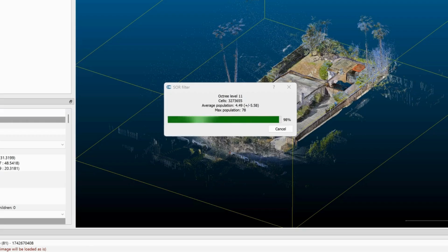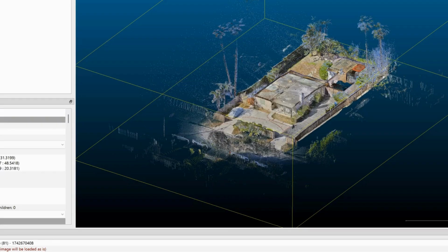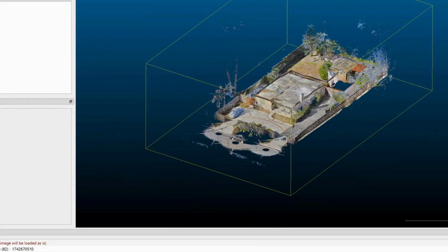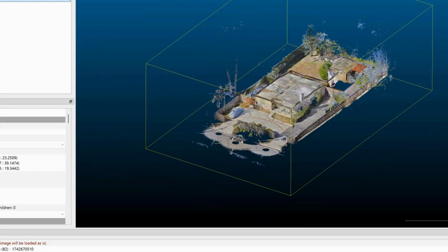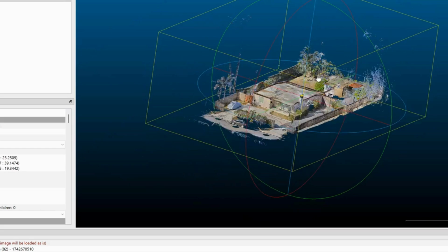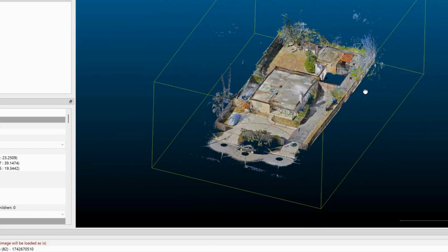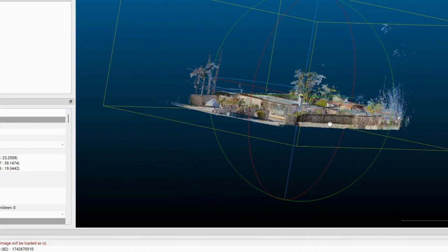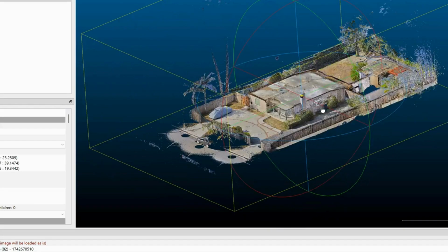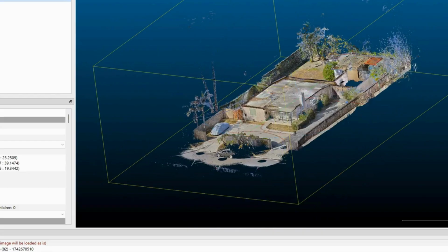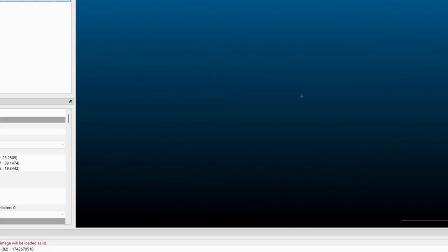And now the way CloudCompare works is that every time you manipulate the cloud, it creates a new cloud underneath it. So right now, it still retained the old one, and whatever I just did, it created a new one. And sometimes it'll give it a new name. As you can see, a lot of the noise got erased automatically, but it kept a lot of what was there before, and it just gave it a new name. So this is almost the way.